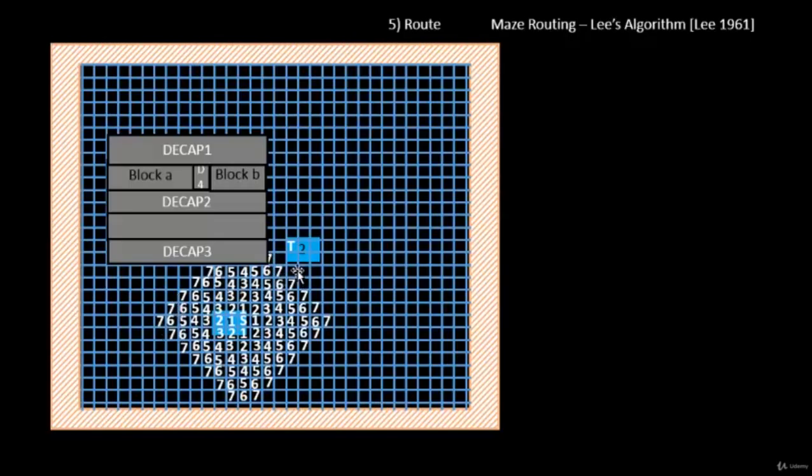Okay, and so on. Next we have to look into the grid boxes with the label 7, and label the adjacent grid boxes as the next integer, which is 8. We have taken all the 7s, and over here there is a limitation. We can't go inside this area because this is again a logical blockage. Remember, in the first section of the first video, we added this particular logical blockage so that no logical cell or routing comes into this area, because this area is reserved for pins. That's why we put a placement blockage over here.